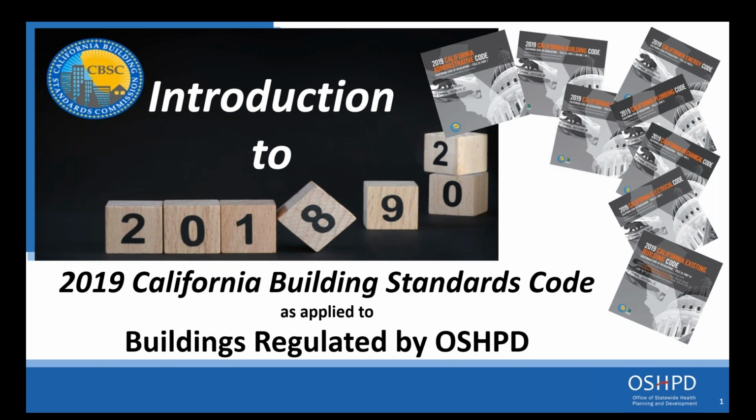They can be a source of infection, and you have to think about what they're doing. I recently saw a project where they had 3 operating rooms going in. The third one they were going to keep as shelled space, and in that they were going to actually put a positive pressure into it because they were going to ventilate it as though it was still a functioning operating room, in which case you would take contaminants from that room and force it into the adjacent operating room or adjacent spaces like a clean corridor. So it varies.